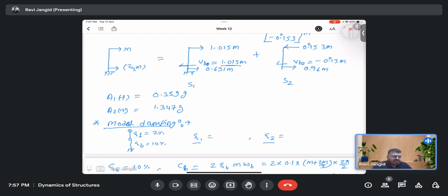And then at the end, they have combined the response of the first story, and to find the maximum response they have done the derivation with that, and they are getting the t value, and at that t value they are getting the values. Okay, no, I take directly M1, I didn't take M1 M2. Yes, you should take the capital M1 and capital M2, not the direct story M. Then we will get the answer, right? Yes, you should do capital M1 equals phi 1 transpose times the mass matrix times phi 1. Understood.